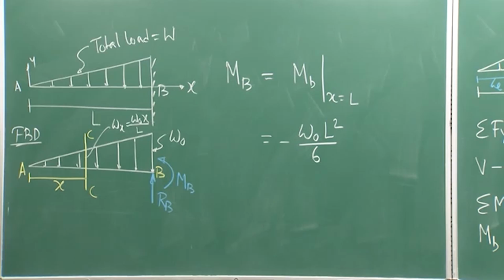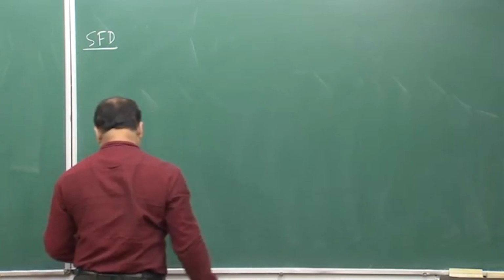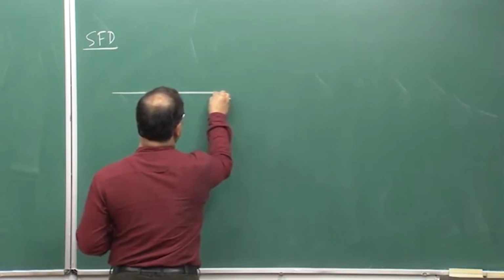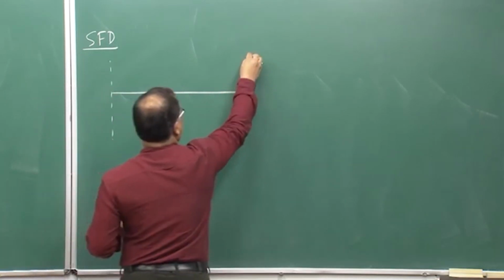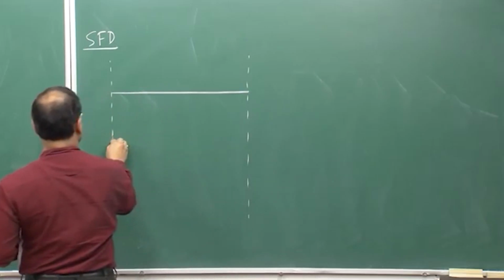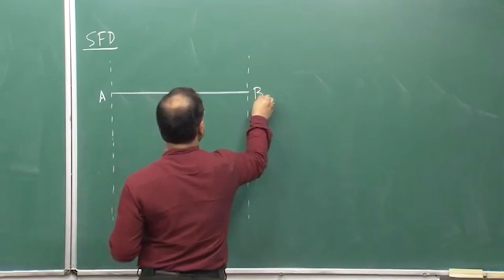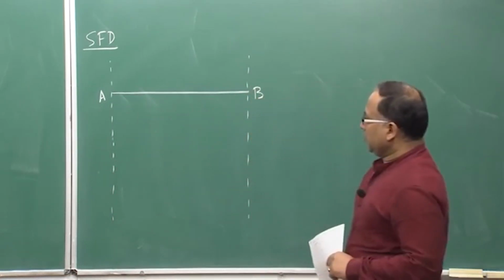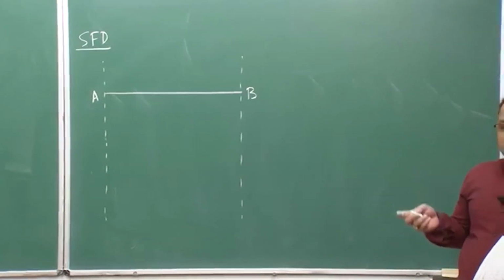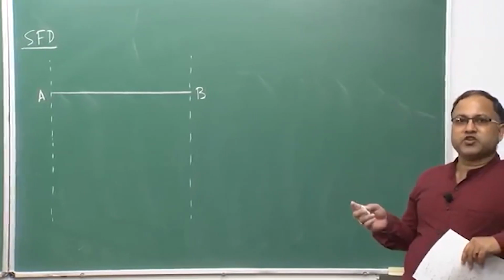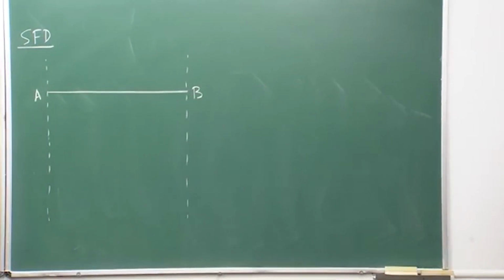Okay. So, now we are going to draw the shear force and bending moment diagram. How will it look? First, we draw the shear force diagram, SFD. This is your baseline, points A and B. If you see the expression, only one section will be sufficient to define the complete variation of shear force, because here you are not getting any change in load; this is a continuous load.